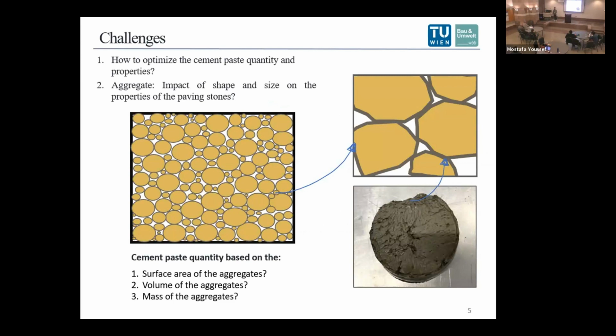We started by assuming that all particles have a spherical shape in order to calculate the volume. Then for the same grains, we took approximately 100 grains, took pictures and analyzed them with imaging. And for the same grains, we measured the real volume with a pycnometer. So the difference was above 50%.